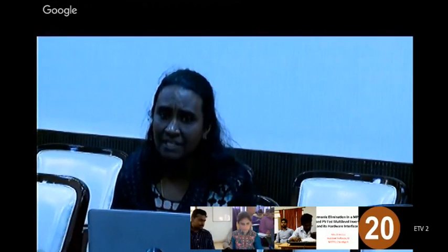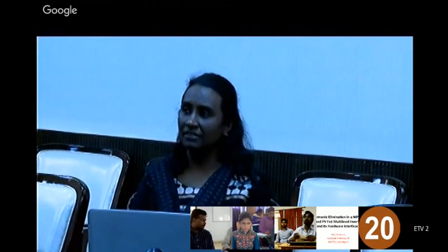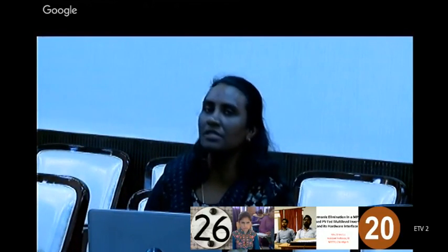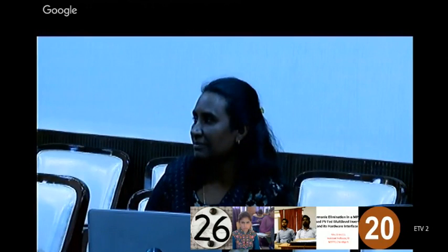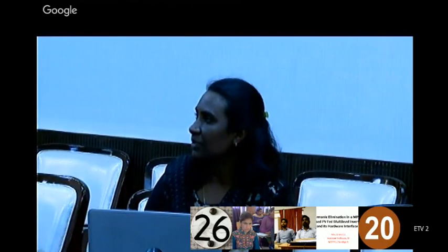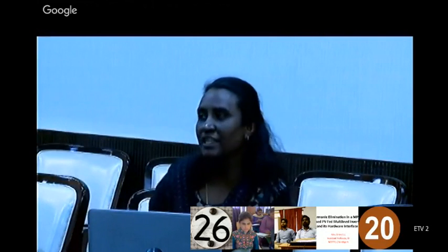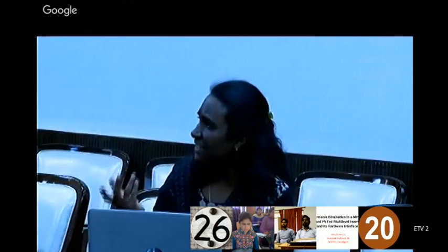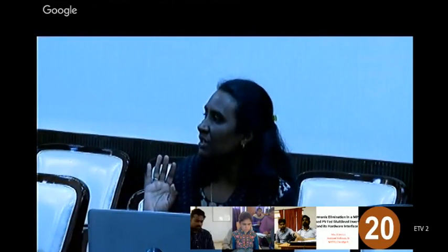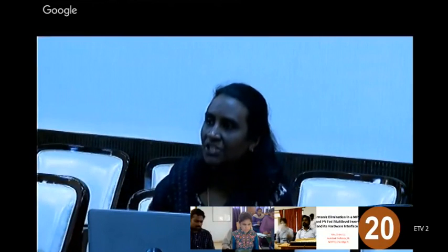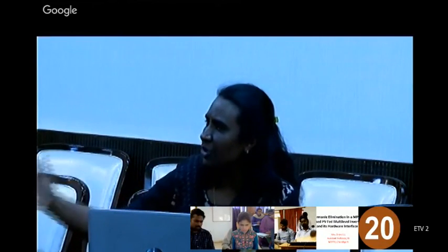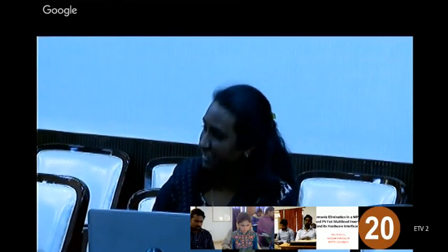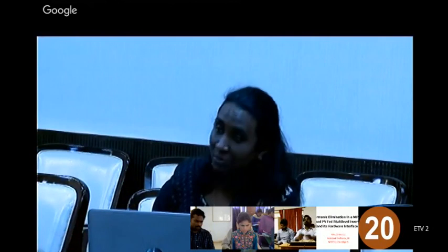Can you tell me some methods by which you can eliminate THD? Harmonics, if you want to eliminate the harmonics, how can we do this? Okay, one is by modulation technique, one is by filtration. You can have some filters, LC filters or hybrid filters, active, passive, all these filters you can use. And one person has said modulation technique. So which one is best? Can you go for modulation technique or filtration? Yeah, some places use both also.